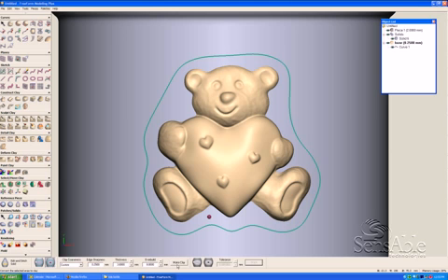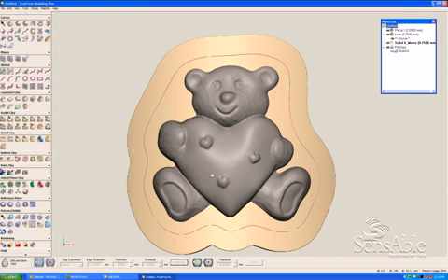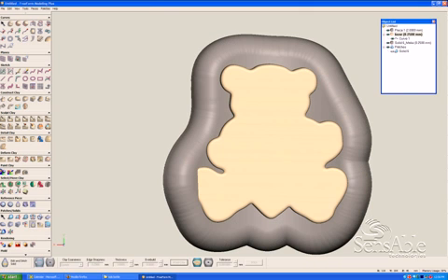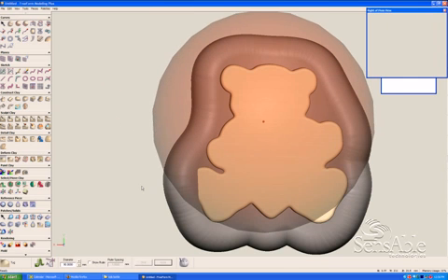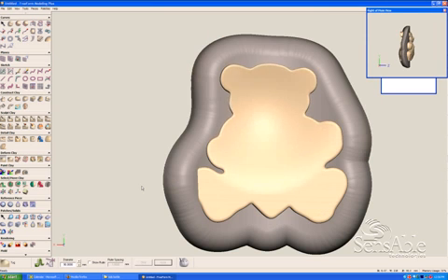So what I'm doing now is creating a trim line for this model, and I'm going to delete the inside of this surface on the baby's bottle and thicken it with an overbuild to a voxel geometry. The reason we've thickened it with an overbuild is so that we have a substantial amount of geometry with an overlap, so that when we do create a surface, we have some overlap to trim and then stitch the surfaces into the model of the baby's bottle.